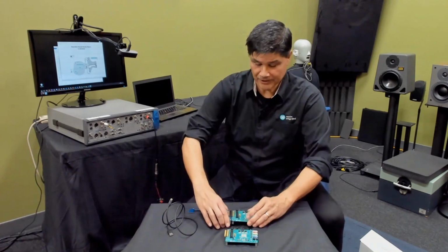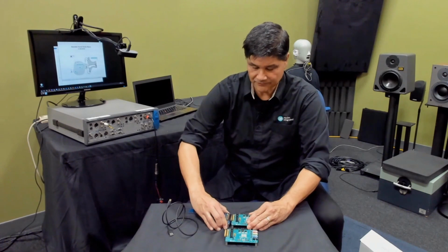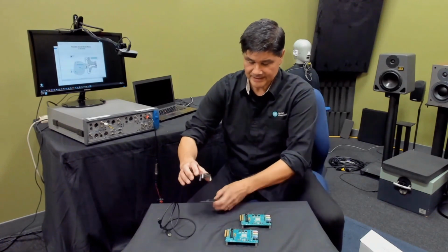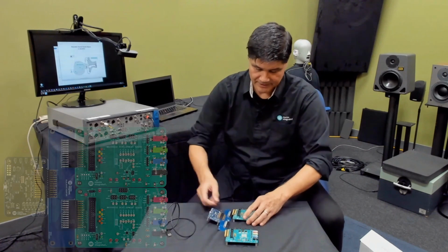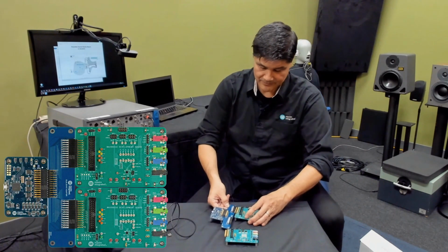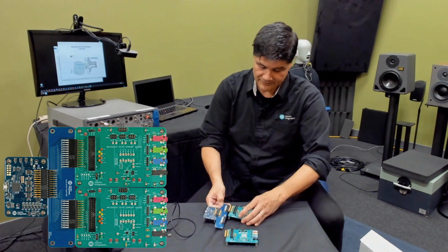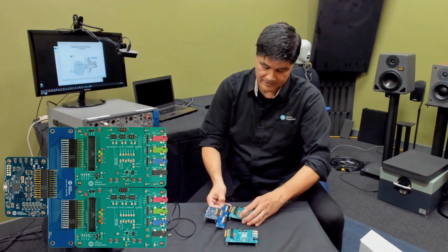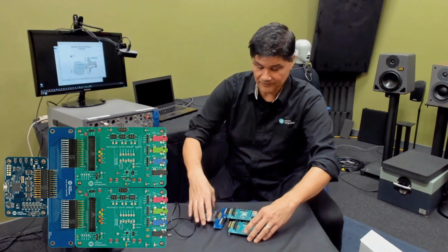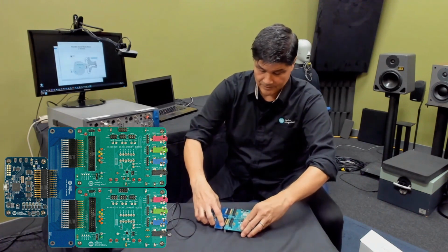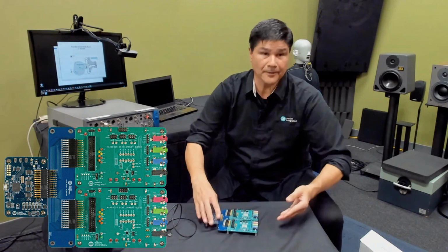To do a stereo configuration, you unplug the audio interface board here, and you plug this instead into the dual EV kit adapter, and then you plug the 2 EV kits into the dual EV kit adapter. What you have now is that the development systems are identical again, but they're set to different addresses, so they don't conflict on the I2C bus. So that's how you'd set it up for stereo.